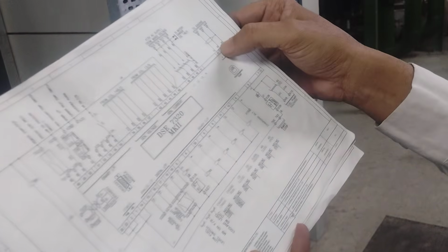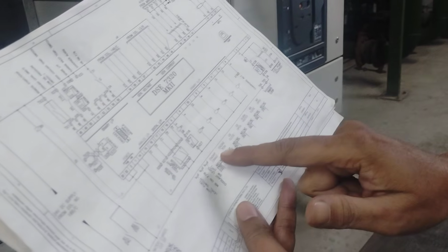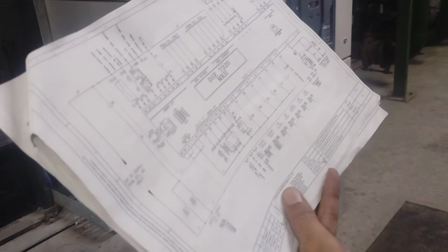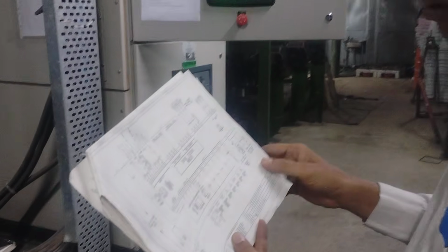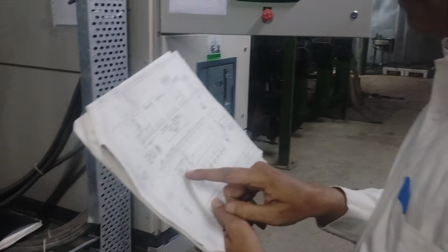These are the MPU sensor for speed controller. These are the remote start, stop, breaker control, breaker on, off, and engine crank, engine run. These are the analog inputs for oil pressure sensors and coolant temperature sensor. Oil temperature sensor is for VDO 10 bar. This is a diaphragm based transducer and sensor, and this is the coolant temperature sensor PT100.